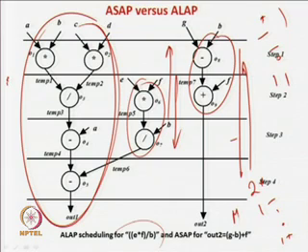So, your m is given to be 4, that is assumed. Within this m equal to 4, you cannot move these operations. So, you can either select as soon as possible or as late as possible and fix it. Okay, that is actually saving some of your computation effort. If you think that in the whole circuit first I will try as soon as possible, then I will go for as late as possible, then I go for some hybrid in the whole part of the circuit, that will actually take more computation time.